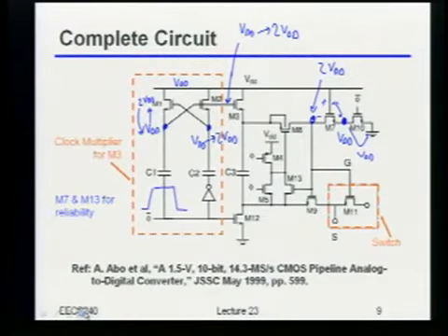Okay, so now we at least know how to get relatively constant resistance out of our switches. By the way, this isn't actually completely perfect, because even after I've done all this, unfortunately you still have that body connection there. So you're still going to have variation in the resistance because of the body effect. But once you've done this, you can get really, really high resolution sampling up to some pretty high speeds. So that's usually not too big of an issue, but keep that in mind because it's not perfect either. So we have a good idea of how to get high resolution, high speed sampling.